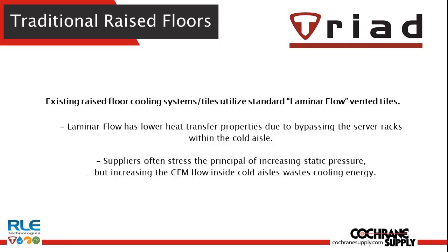So a lot of existing raised floor cooling systems leverage standard laminar flow vented tiles. It has a lower heat transfer property due to the bypassing of the server racks within a cold aisle, so suppliers will often stress increasing the static pressure. But if you do that, you're wasting fan energy and cooling energy to increase the CFM inside of that space. Given what all data centers are trying to accomplish is reduce that energy consumption and lower their PUE because they're already using plenty of energy.